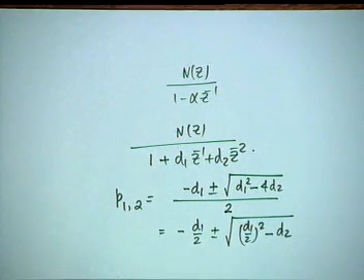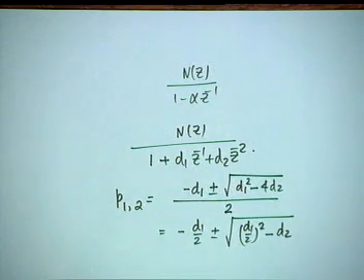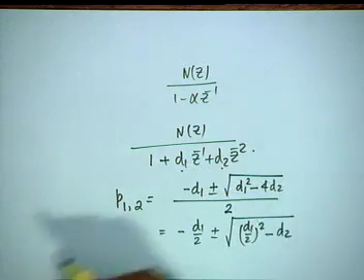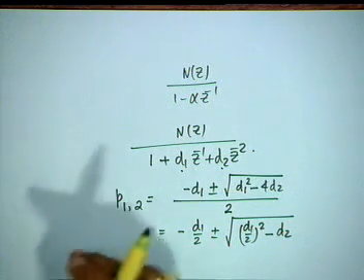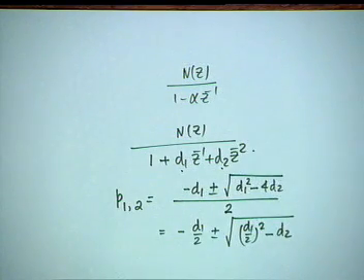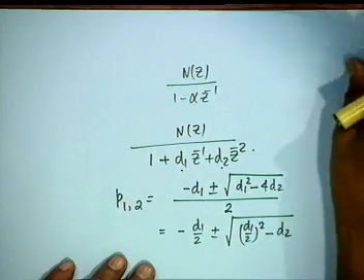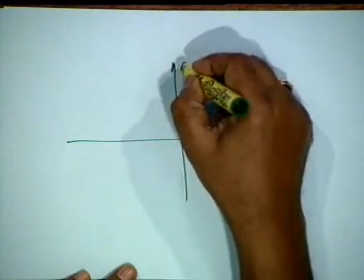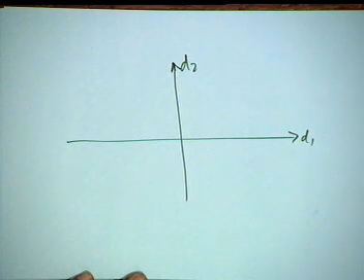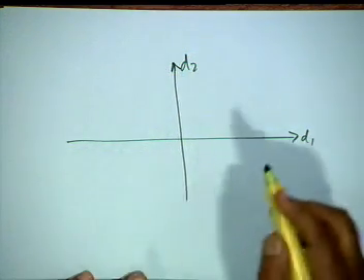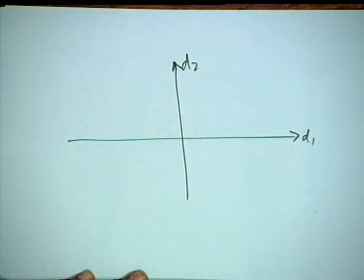Now, once again you will have to find these roots, and again numerical accuracy or inaccuracy does come in. But given d1 and d2, can you say immediately whether the filter is stable or not? This would be possible if we can have a plot of d2 versus d1, if we can demarcate a region in this d1, d2 plane, it is a parameter plane, such that inside this region the second order filter is stable, then you do not have to find the roots. Given d1 and d2, you can immediately say whether they are stable or not.